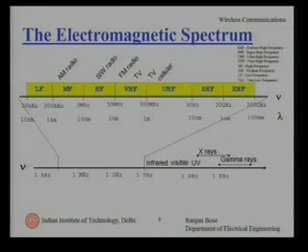Certain frequencies, for example, the 900 megahertz travels to quite a distance. Lower frequencies also travel large distances. Therefore, a TV tower and a radio tower can cover areas up to 5 or 10 kilometers, if not more. A typical 900 megahertz base station, which communicates with our mobile phones, can work easily up to 5 kilometer radius for the given power. But for the same power, if we increase the frequency, see we go to 2.4 gigahertz, the electromagnetic radiations will get attenuated much more. That is, our coverage area will get reduced. Let us go to still higher frequencies, for example 28 gigahertz. Right? There also our range comes to about 2 kilometers.